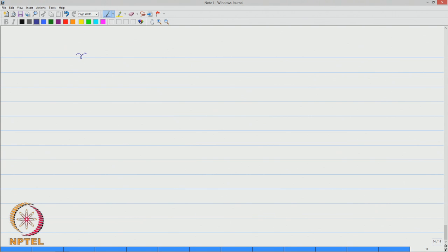Now, I can find the reflected overpressure clearing time, which is Tc, which is 3S by U, which is 3 into 5 by 398.172, which is 0.0376 seconds, which is less than Td.